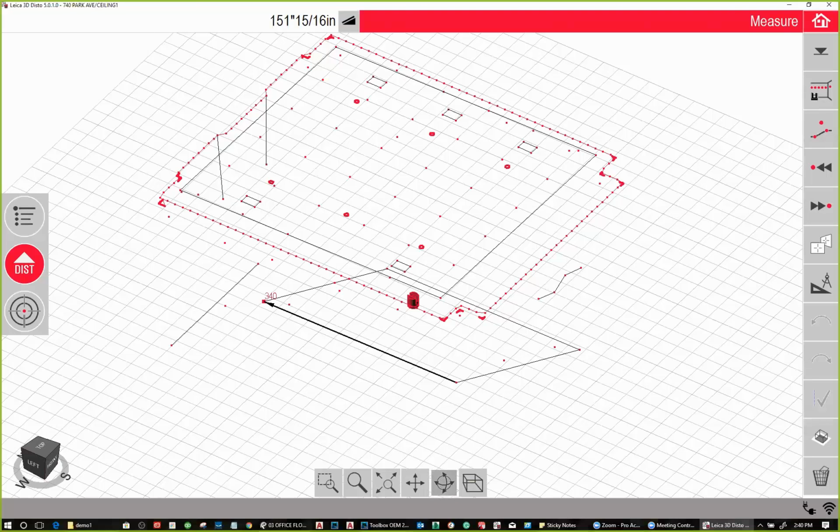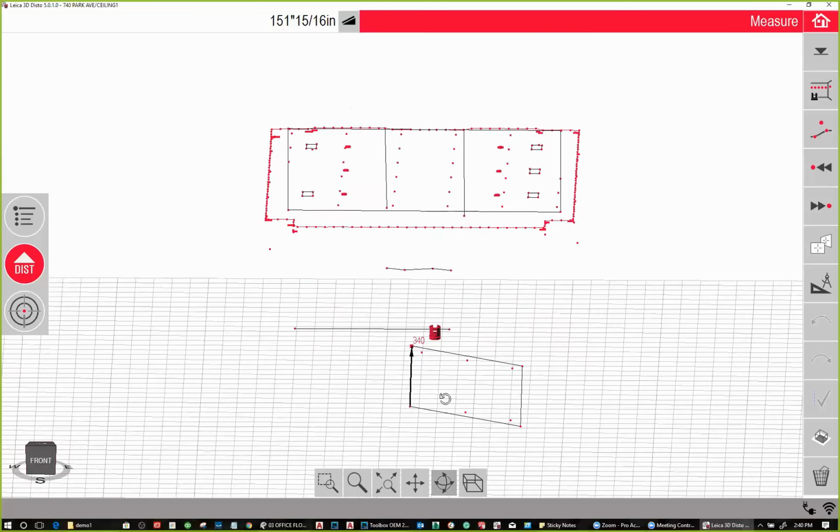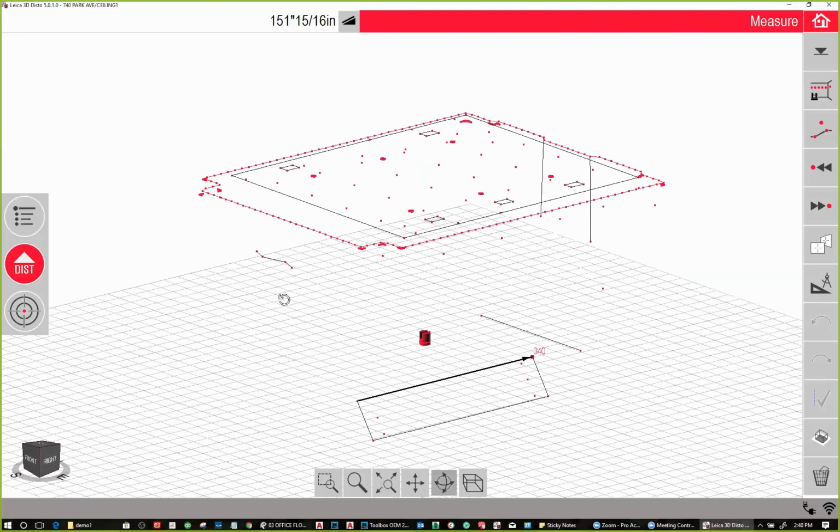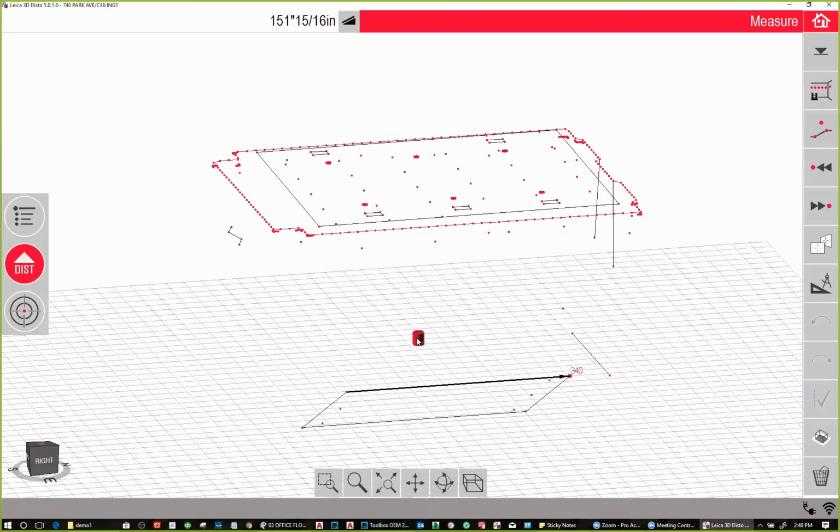And then if you'll notice, around the perimeter, just a little bit lower, about 12 inches lower than the ceiling, there's a whole bunch of points. And these points were the seams of the paneling that he had previously done that we had to match up with. So I was able to set up the Disto in one location and basically capture this data and then bring it back into the Microvellum AutoCAD environment to then incorporate all this information into the drawings that were created.